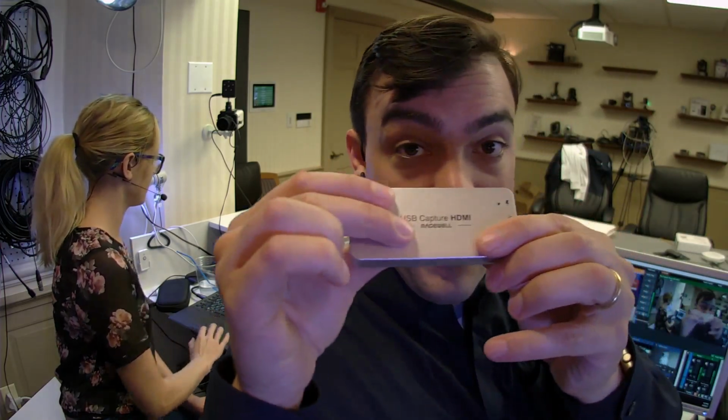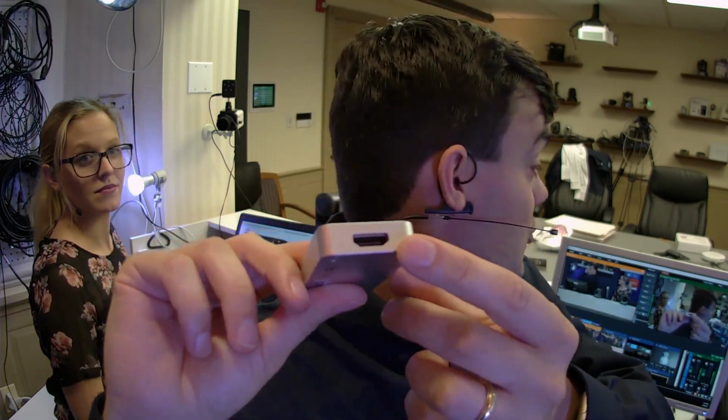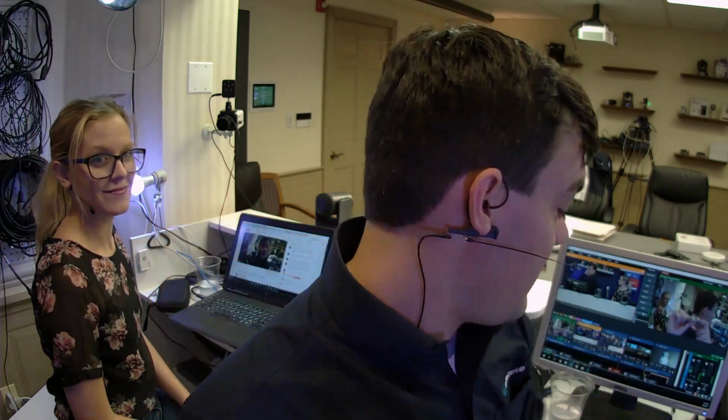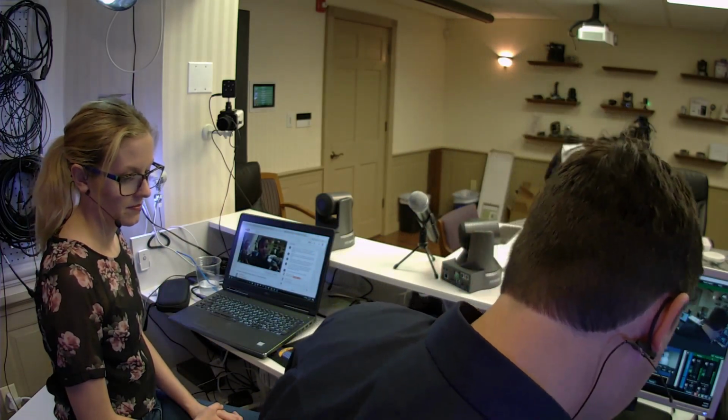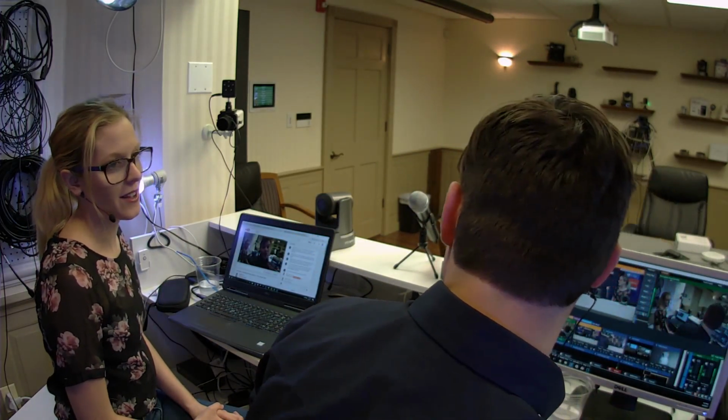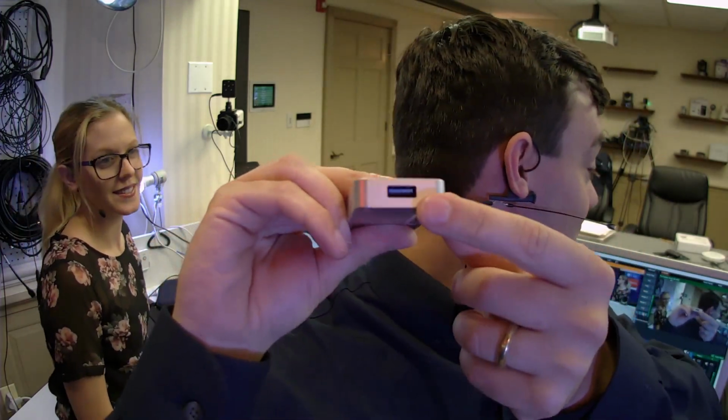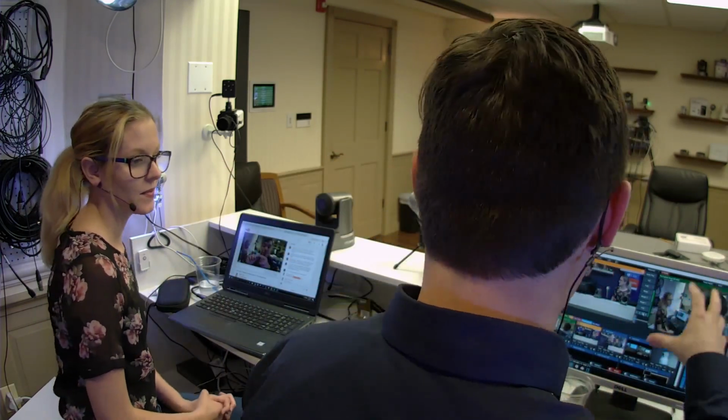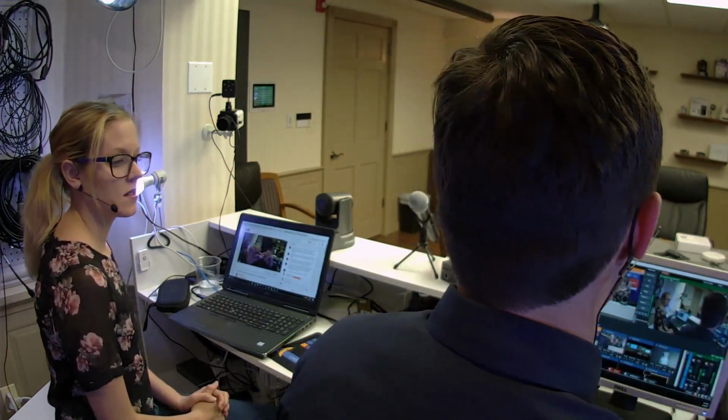I know that's a lot of letters and probably not the way most people will use it. Most people will probably take the HD SDI feed from the camera, which can go up to 100 feet, very high quality plenum rated cabling. You can run it in the ceiling, no problem, and then plug it into an HD SDI frame grabber. This frame grabber will convert it. That's an HDMI version, but there's an HD SDI version. Let me see if I can find one. We've got them all over the place. It's probably a lost cause for today. You can see right there at the bottom, that goes to USB 3.0, so that way you can bring it into Skype or GoToMeeting or WebEx.